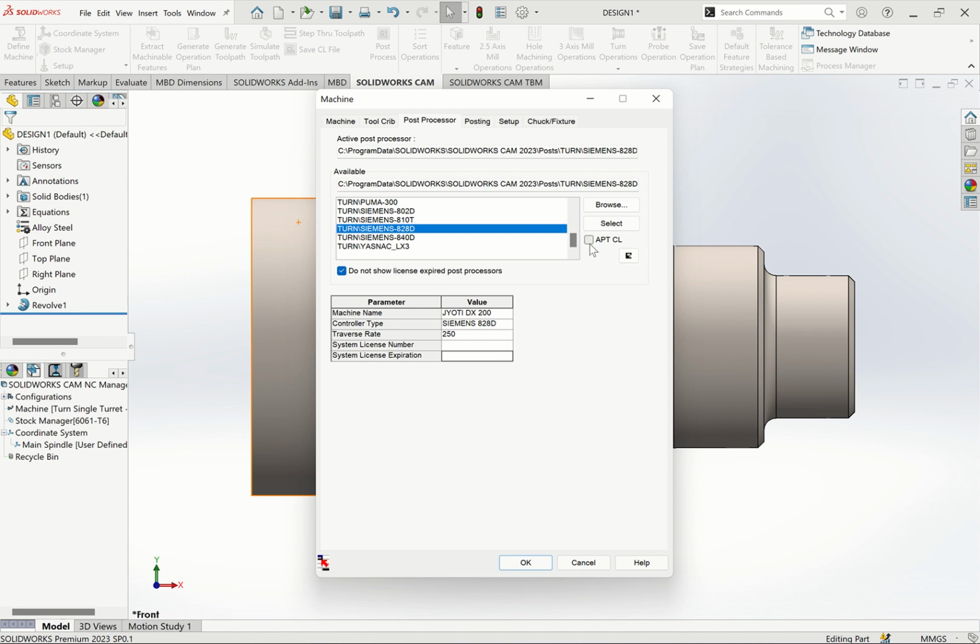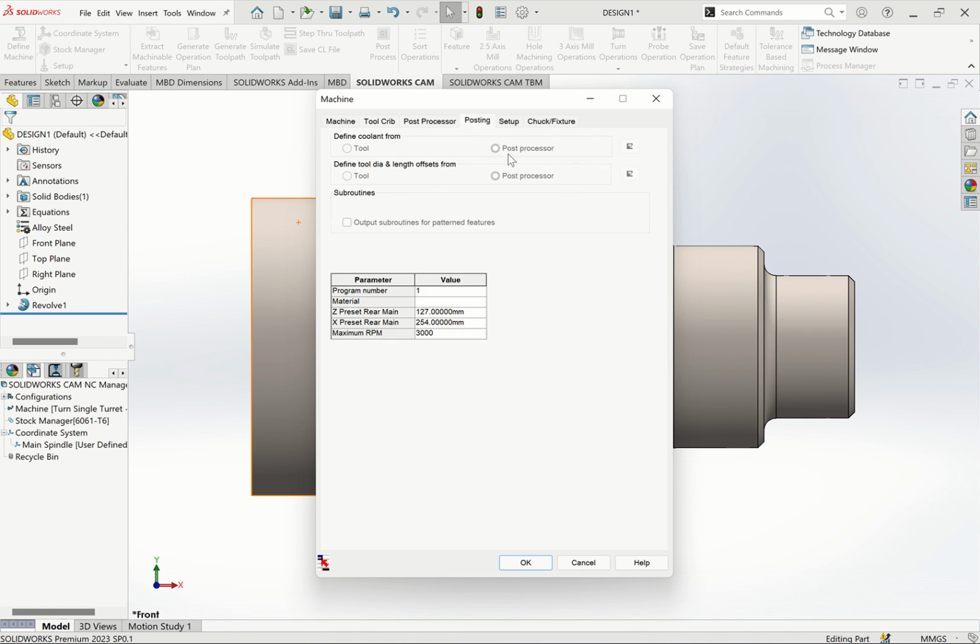That is the automatic pallet tool controller. You can put all those in, but in case it doesn't have it, you can go to posting. This one already has all these parameters put here. Now the maximum RPM you can use, you can edit here. The maximum spindle X feed rate or Z feed rate, and the maximum distance it can move along Z and X, you can include all these parameters here.